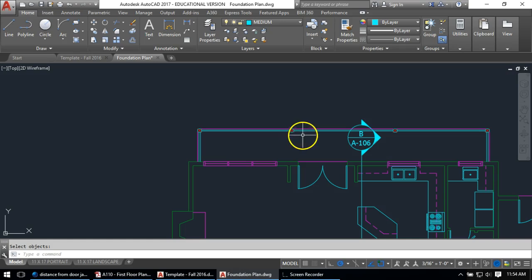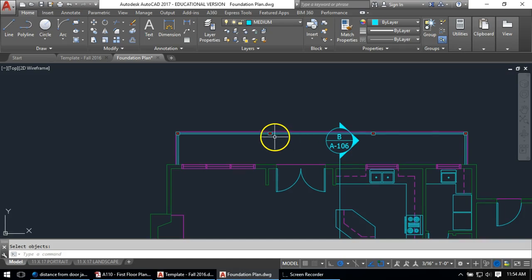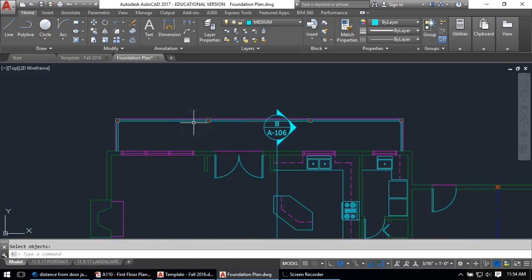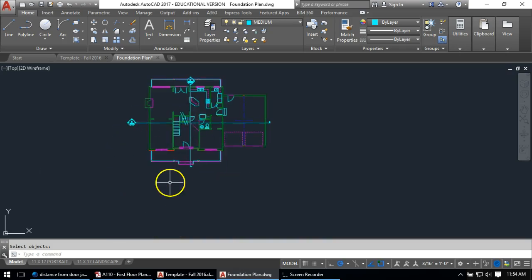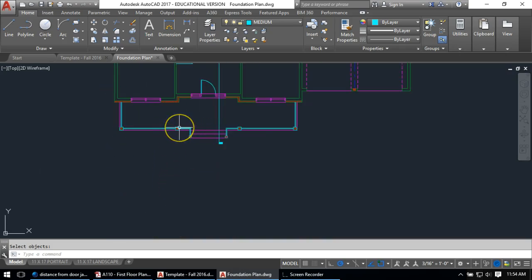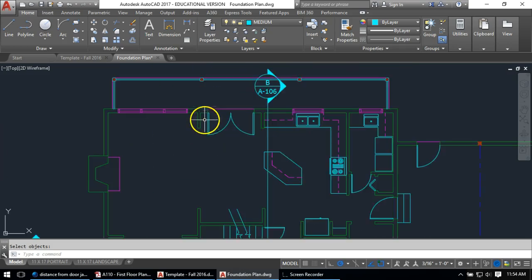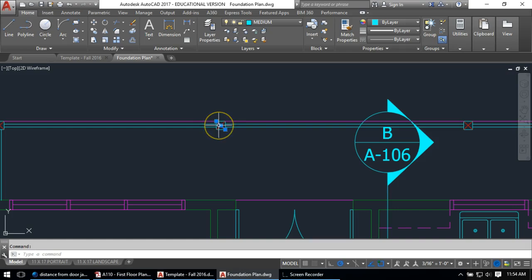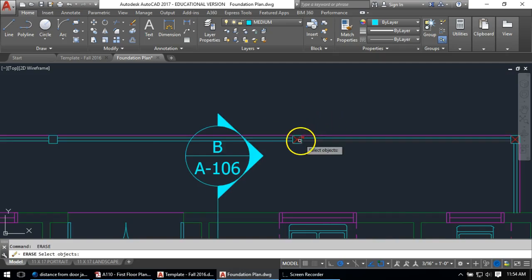There's actually a couple posts for this. Actually, these posts are different. I guess this is just a railing post. I see. Yeah, so this is not sitting on the columns because it's not structural. I use the circles here because this is probably holding up a roof, and I can tell that because it says covered porch. This back deck is not covered, so this railing does not need to be structural, so it does not need to be over the foundations. So we can see that they indeed aren't over the foundations.